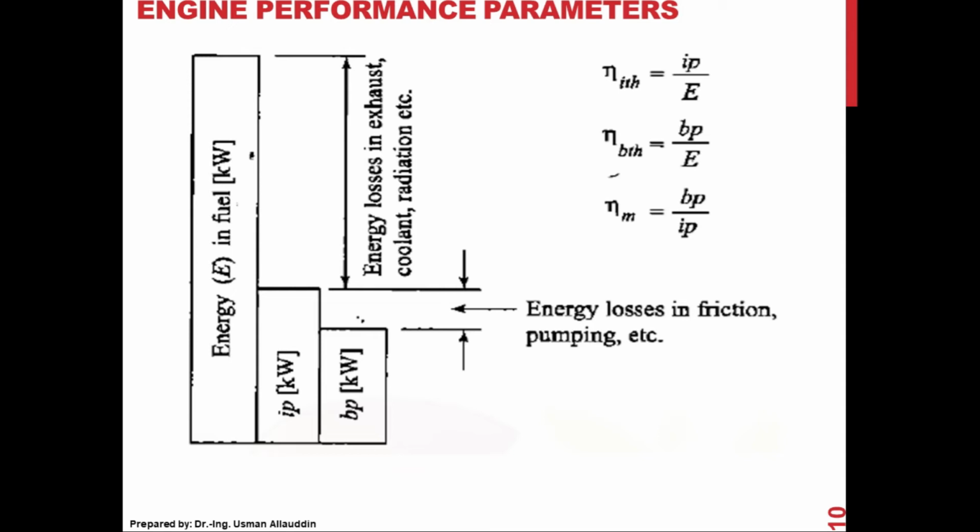So some energy will be lost in the exhaust, and then you need the coolant. Because if you run the engine without coolant, all the parts are made of metals. So thermal expansion of the metallic parts will take place, and ultimately the piston will expand, and when the piston expands, it will be jammed, it will be blocked, it will be sealed in the cylinder, so the moving parts cannot move. So if you run the engine without coolant, this is not possible, so you have to cool down the engine.